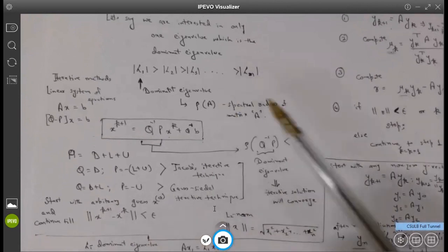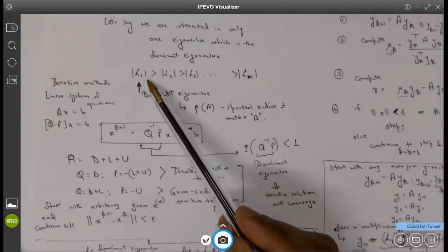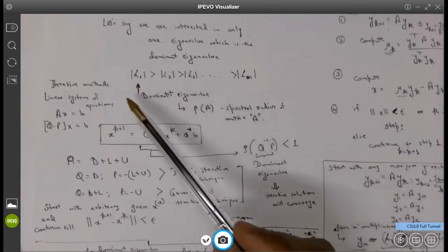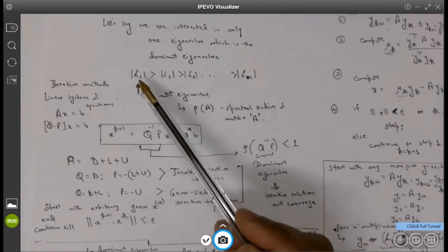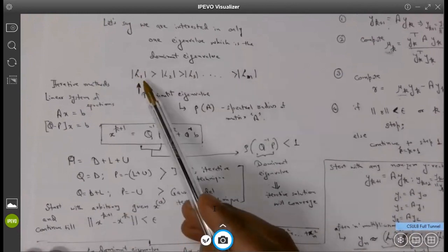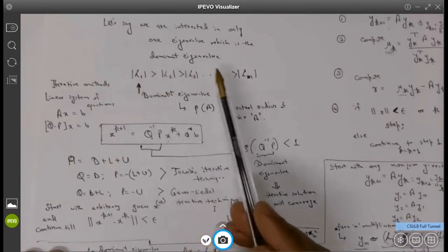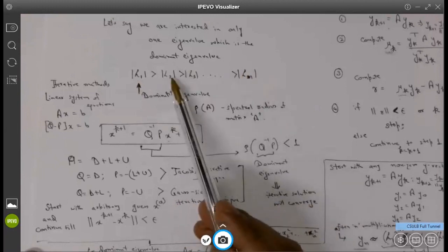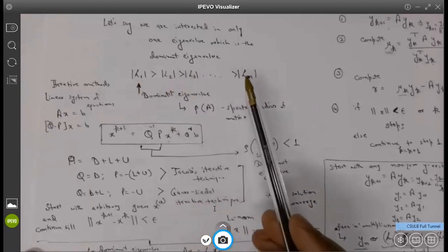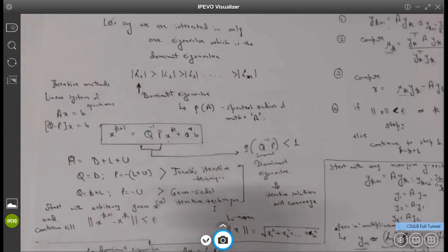Another point of interest is that these eigenvalues in a dynamical system correspond to the natural frequency, or the square of the natural frequencies. And the first eigenvalue corresponds to the fundamental mode. So if you are interested in only knowing the fundamental or the natural frequency, we are concerned with lambda one, not with other specific eigenvalues, because other eigenvalues are called the second harmonic, third harmonic, and so on. But generally the first harmonic basically means it is the natural frequency of the system. It corresponds to the first eigenvalue.